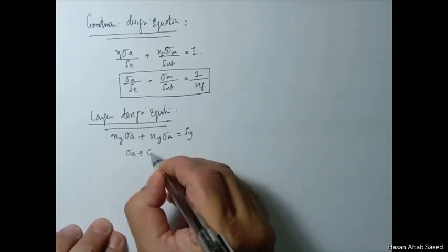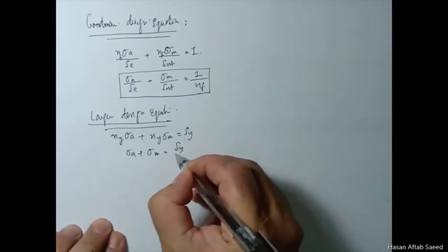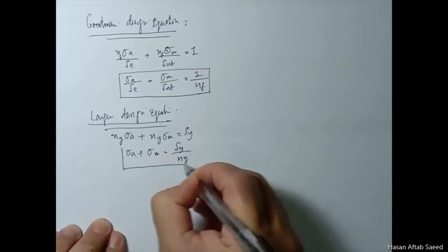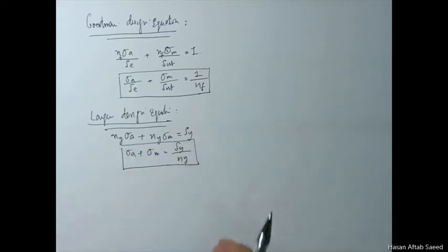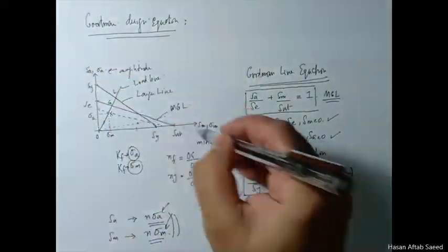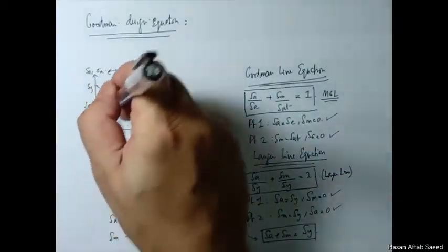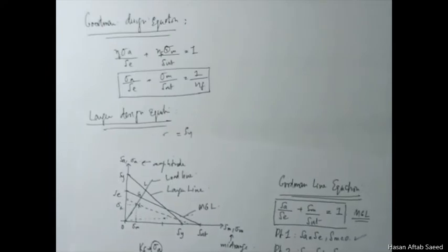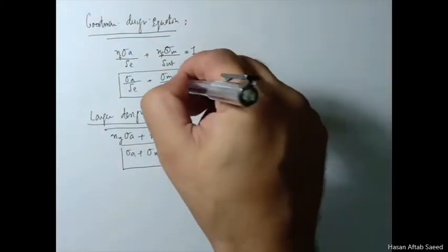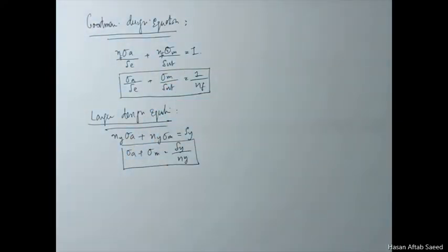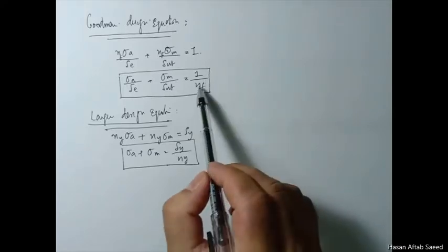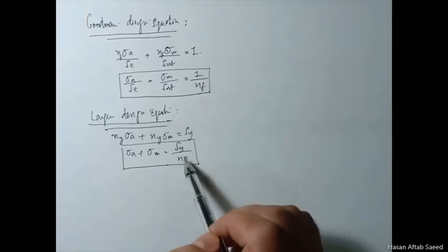And simplifying this, you get your design equation for the line. So instead of graphically drawing this, plotting our point, and then measuring these things, we are just going to use the same quantities in these equations to find out whether our design is safe or not. By safety I mean both of these should be more than 1. NF and NY should be more than 1.